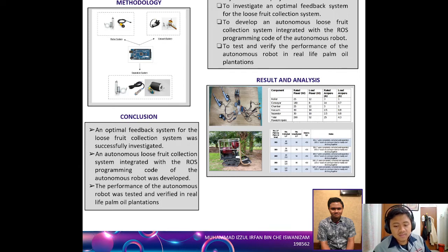However, some improvements can be made. For example, in the roller system, we can remove the linear motor actuator completely and replace it by using rotary encoders. These rotary encoders can be used to more accurately control the position of the roller. And also adding more IR sensors helps to provide more sensitivity of the roller.